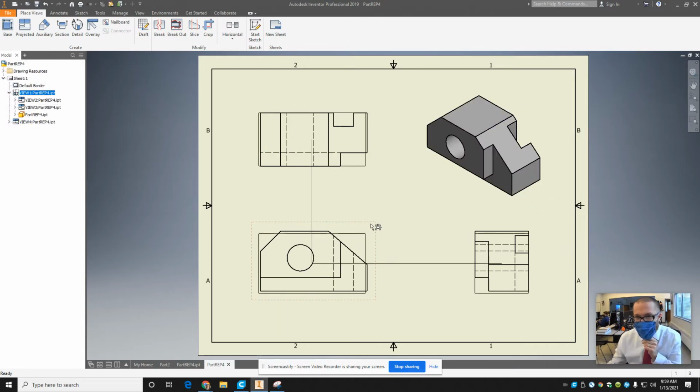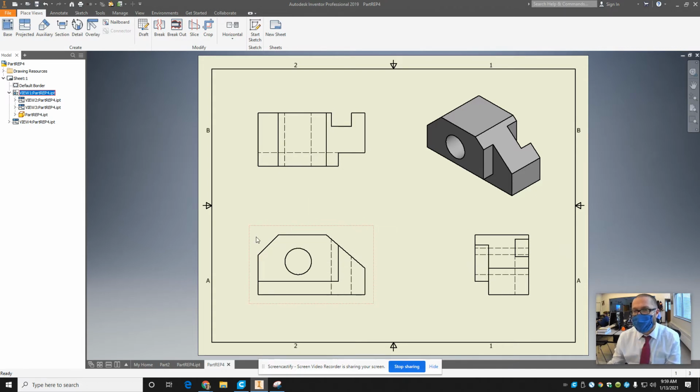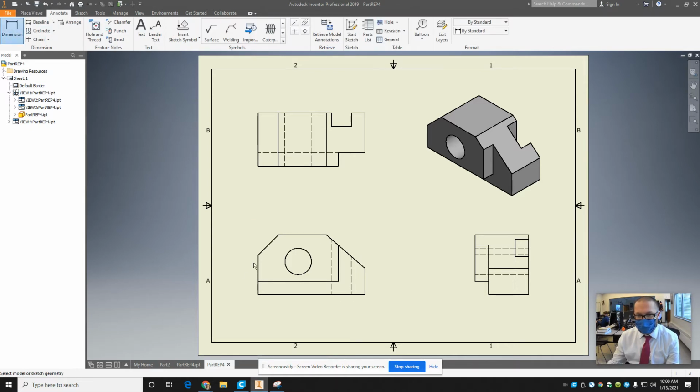All right, remember, you want to dimension things in the contour, you can see them. So, I don't think we used a fillet or chamfer for these. I think we just did it. So let's see, annotate dimensions. Remember, we often want dimensions in the view. We can see the contours, and we want them to be between the models.